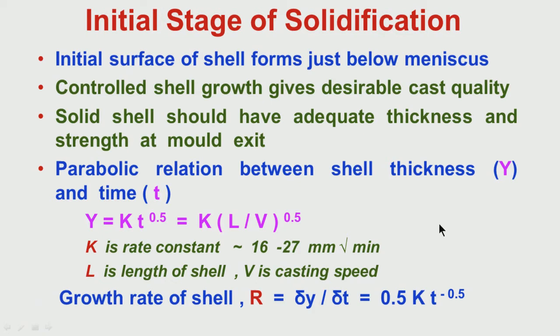which can withstand the stress and strain that are forming on it. It can be solidification stress, it can be when you are bending the mold, when you are straightening the strand, we can have a lot of strain as I have mentioned earlier. So, these are the important issues we have to remember.